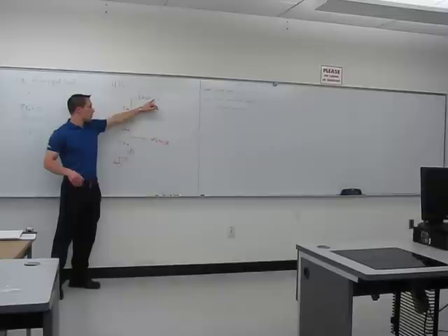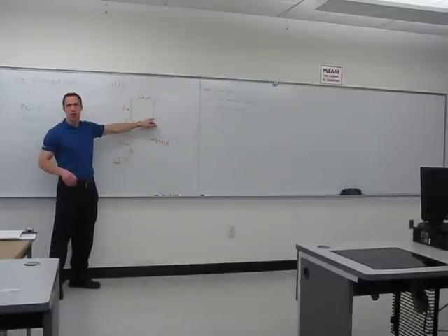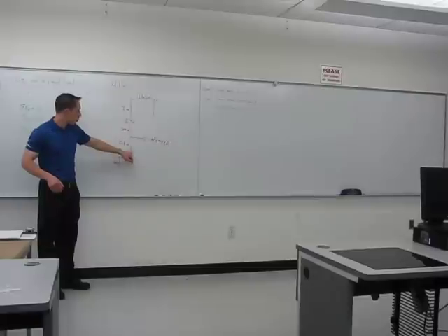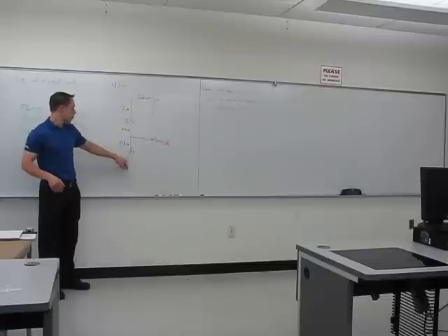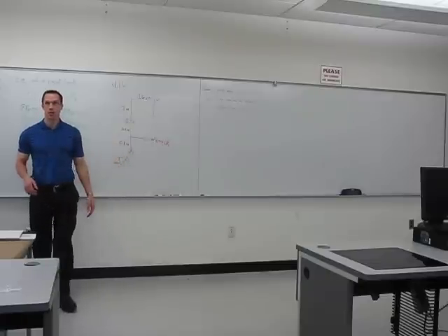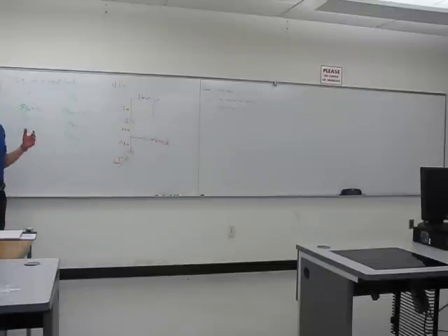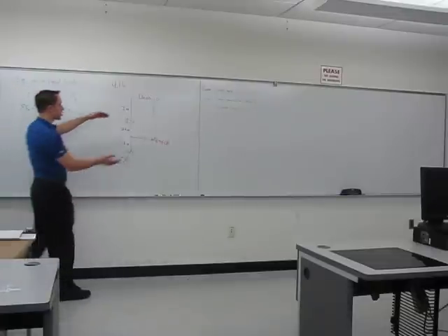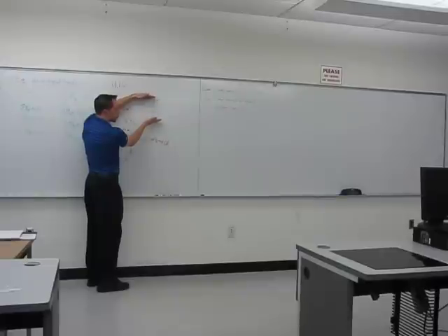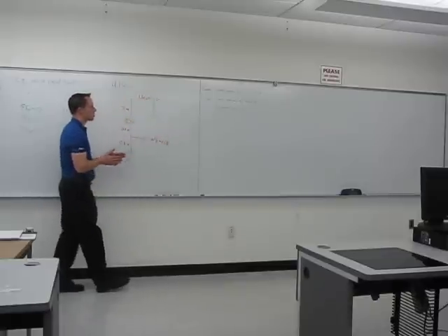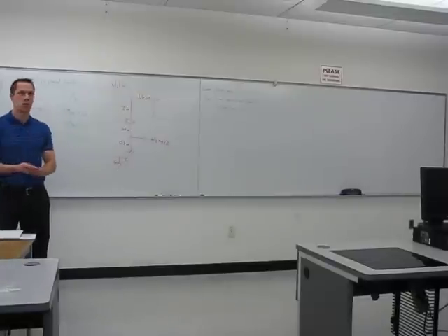But there's a spring over here at D, which is attached to a solid structure. And then we have this roller A at the bottom, which is up against this bigger wheel, which is fixed in place. So we're told that the spring is stretched in such a way that the spring force is 6 pounds. Now, if the spring is stretched from its natural length, remember, it wants to pull back to its natural length. So if it's stretched, it wants to pull back to a smaller length, which means it's pulling down on D. So that's why I could write that the spring force, FD, is 6 pounds going down.